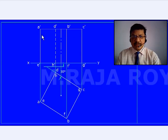Here this is the top base A dash, B dash, C dash and D dash. This is the bottom base E dash, F dash, G dash and H dash. Now here you observe DH, this particular face edge is totally invisible when you are seeing like this. That's why in the front view we have represented that with the dashed line. This is the axis in the front view. This is the axis in the top view.